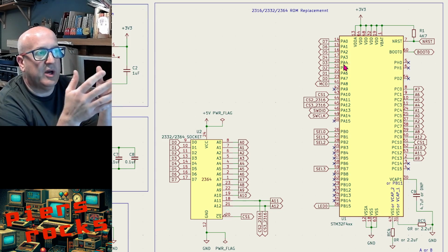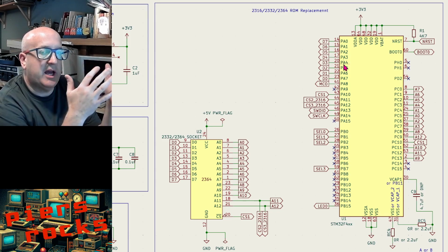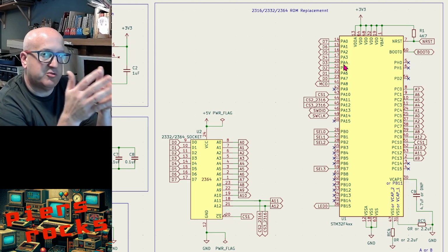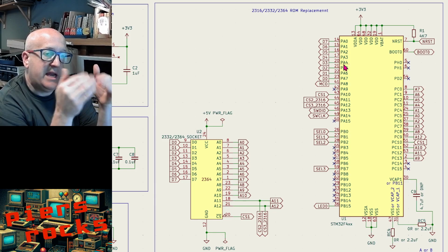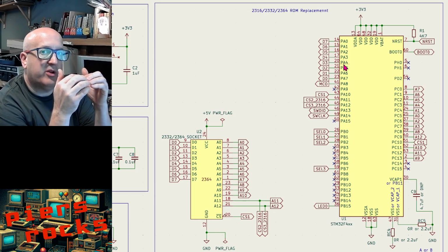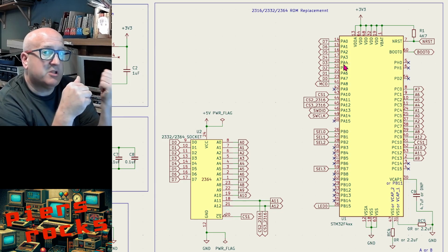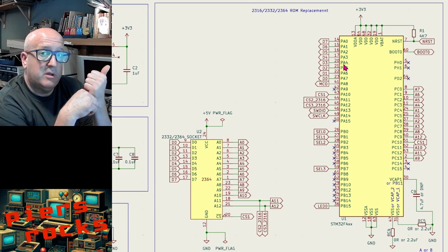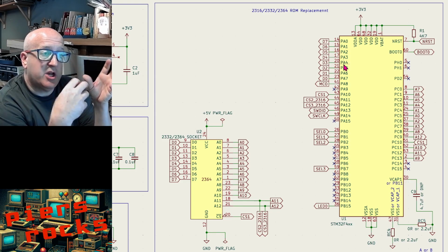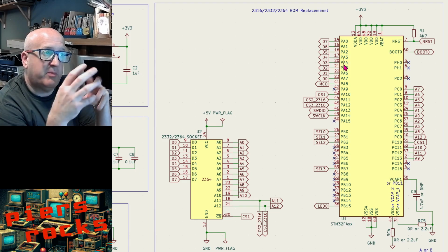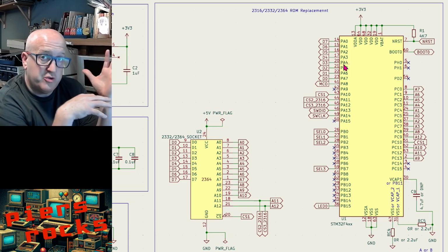One of the key philosophies behind this project is you do as much as you can before the fact, so that the number of instructions, the number of cycles that are executed in the main loop is as small as possible to hit the timing requirements. So anything you possibly can do at build time, you do at build time. So all of the manipulation, and I call it mangling, of the address pins and the data pins is done during the build phase.